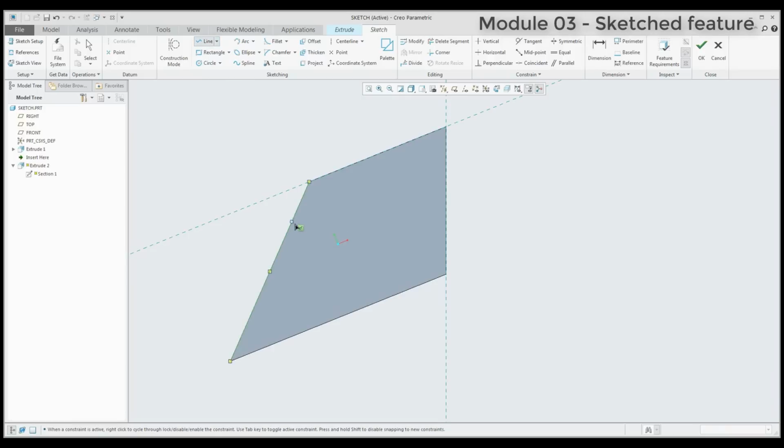You can see here, the system will automatically snap to the existing edge and the system will automatically add this reference. Or you can use the Alt key and select the surface or edge and you will add the reference on the fly. And you can follow and finish your sketch. For example, create standard lines. So here is the answer how to create references on the fly.